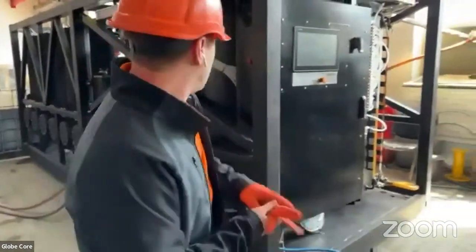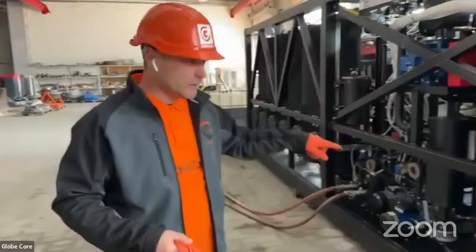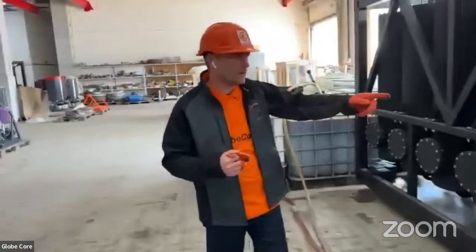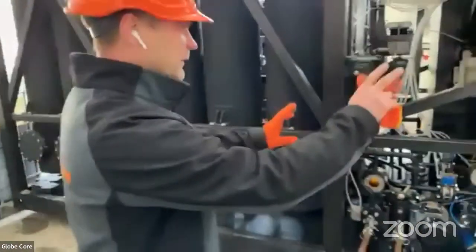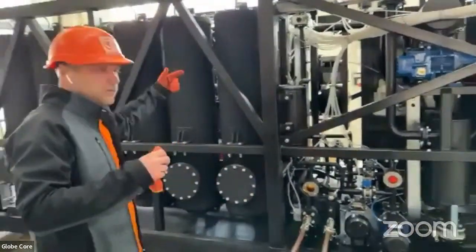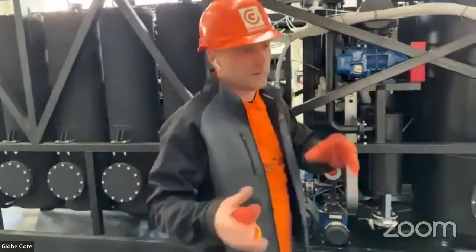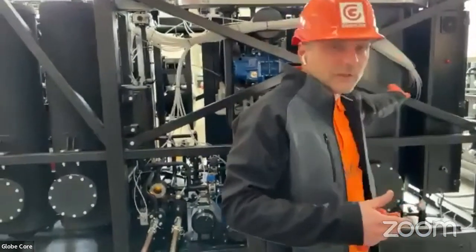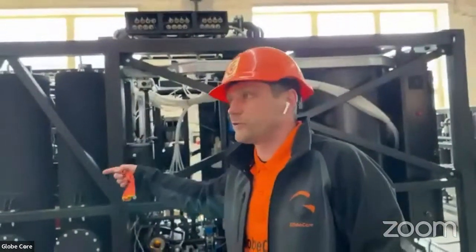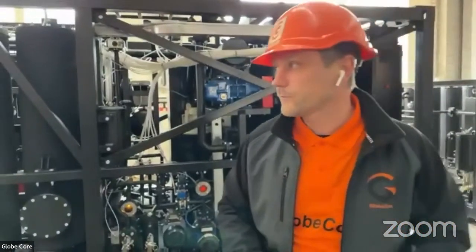The other thing I want to say: to double the capacity of the unit, you can add another section of 12 columns. All the auxiliary equipment is enough to provide normal operation of 24 columns. And the system has the piping, the valves, and the ability to add another section of regeneration columns. In this way, you will double your regeneration capacity.